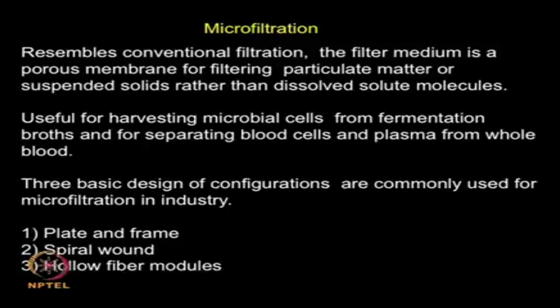Microfiltration now resembles conventional filtration, just like a normal filtration process which we studied many classes back. The filter medium is a porous membrane, so it can be used for filtering particulate material, big material. It can be used for suspended solids, but it cannot be used for dissolved solids.